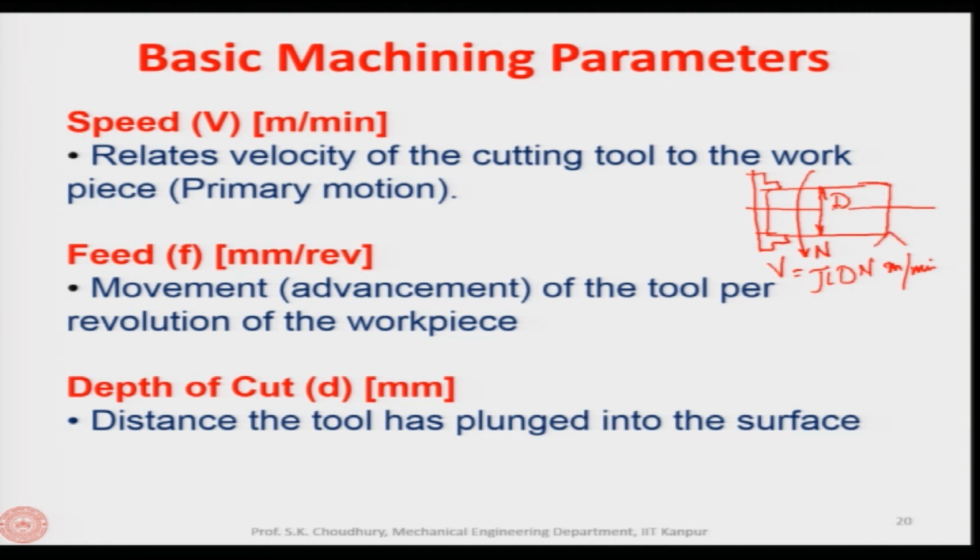Whereas the movement of the tool, for example in case of turning, which moves parallel to the axis of the workpiece, is known as the feed. That means the material is fed to the tool so that the material can be removed. So, therefore, this is called the feed.